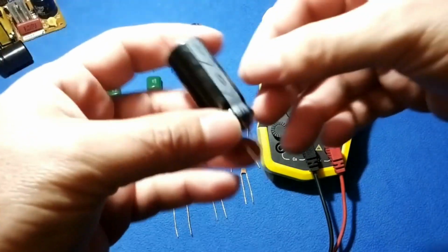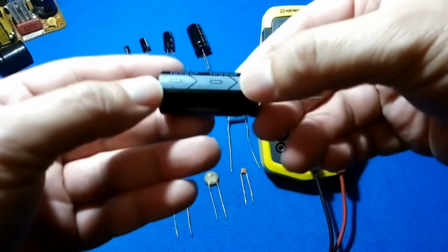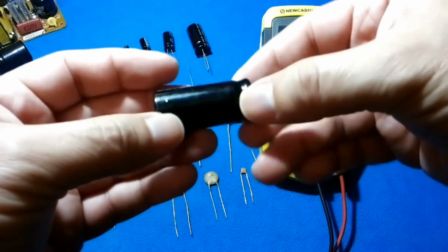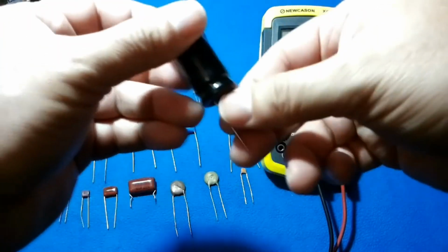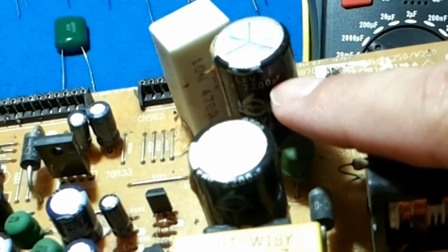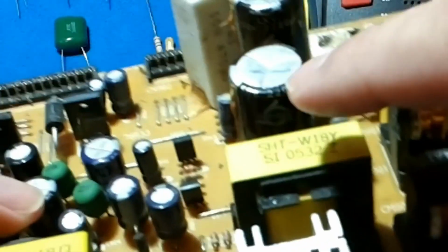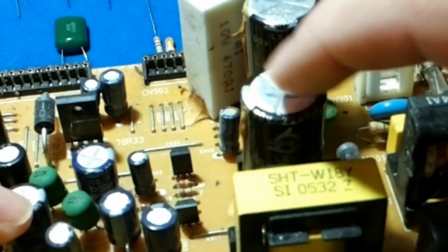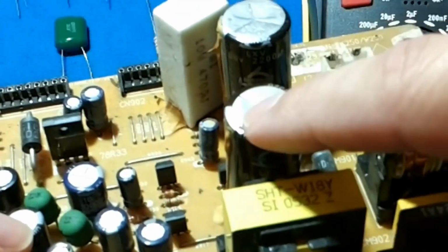Recognizing different capacitor types, including electrolytic capacitors, is vital for effective handling and troubleshooting. Each type typically features specific markings that indicate polarity and connection requirements. Physical indicators of capacitor failure, such as peeling skin or swelling, suggest potential overheating and imminent failure. Regular inspections can help in averting hazardous situations in electronic devices.